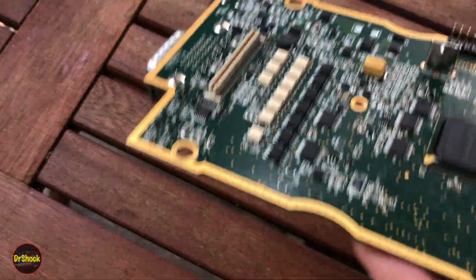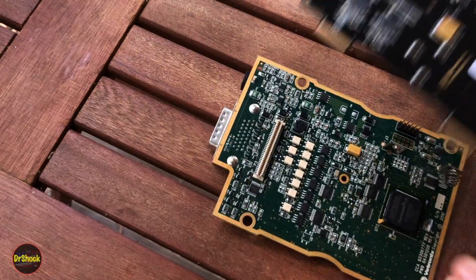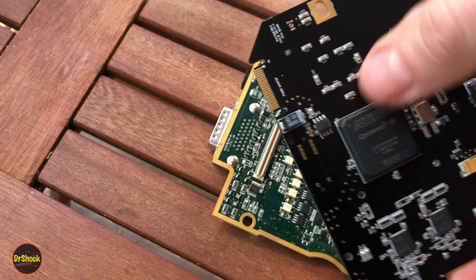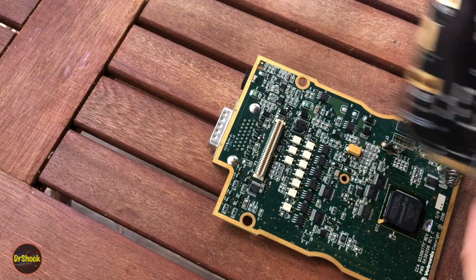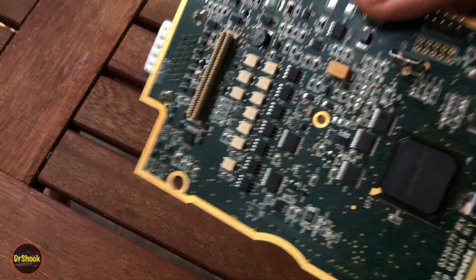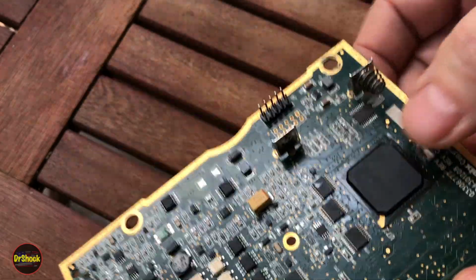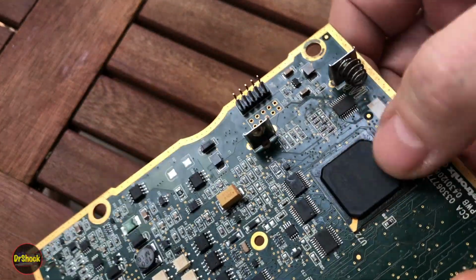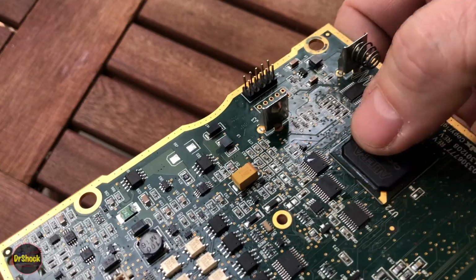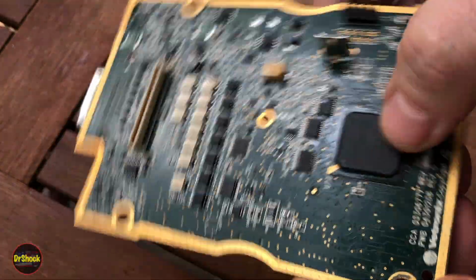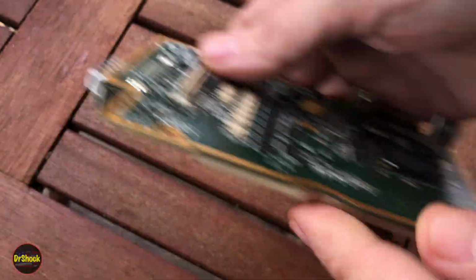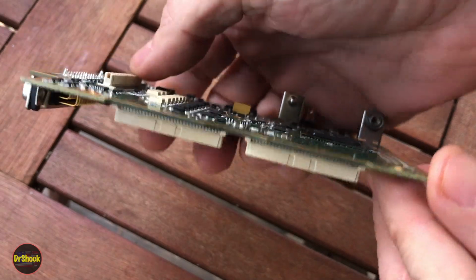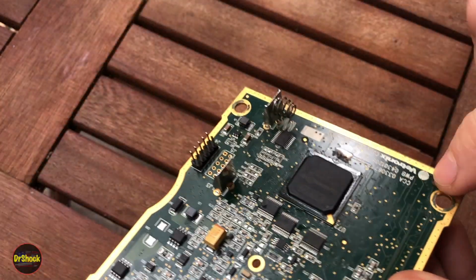Now, the reason I know it's not the profile is I was working on this other board before this that also has a Cyclone 2, although it's a different part number, and this guy came out fine. So we just basically applied the same profile to the MDI's board, and right when we were thinking it should have been liquefied, it was the underfill that was preventing it from coming out when it should have. And then what happened is it started to push these balls out as it looked for an exit path out of the device. If you remember, this board was sitting at just a little bit of an angle because of our board heater, so it had a tendency to run up along here.